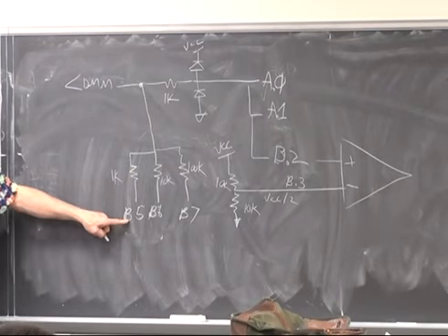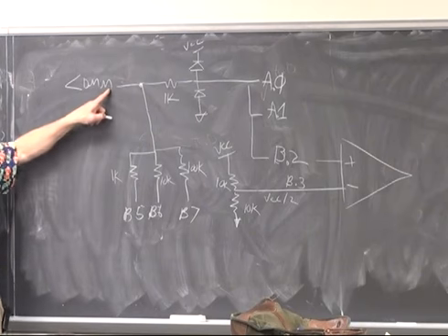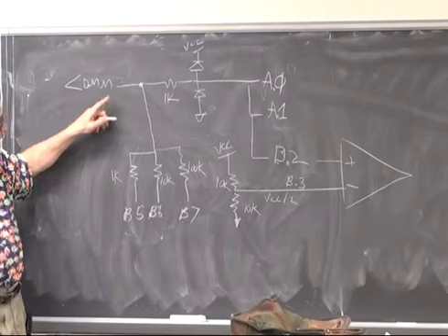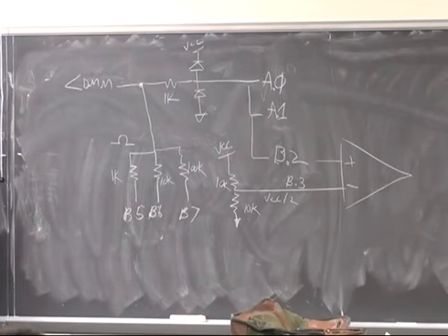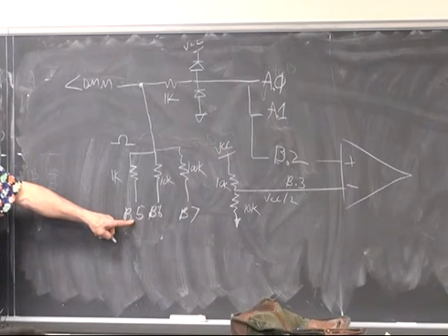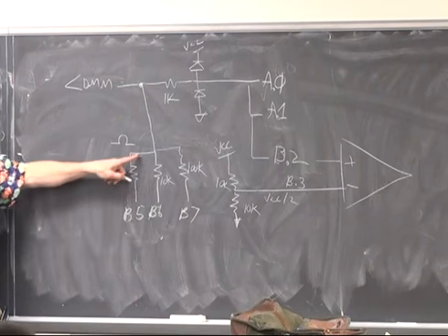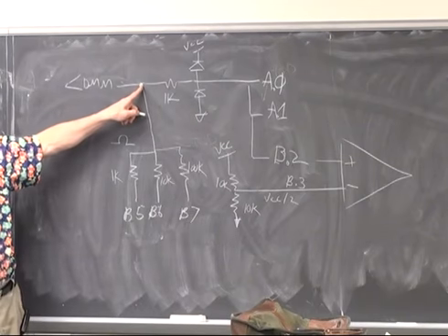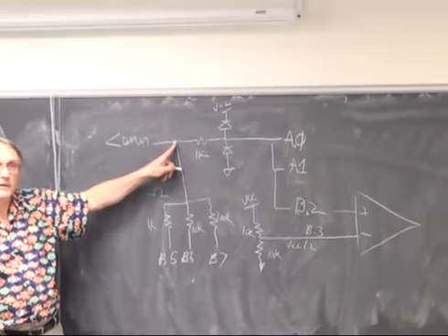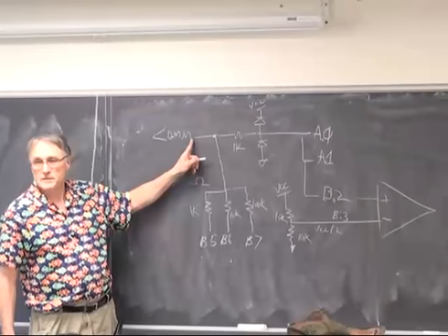These are used to selectively inject current into the device under test if you're in resistance measuring mode. If you're measuring resistance, you connect these to 5 volts using the output pin drive, setting them to a high voltage. That drives current out through the resistor you've attached to the digital multimeter. By reading the voltage here and doing a voltage divider equation, you'll know what the resistance is.